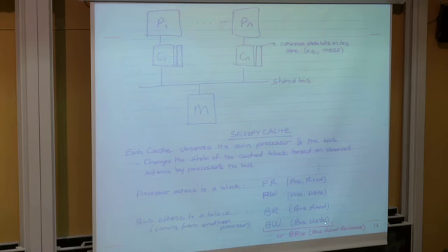Bus write can also be called bus read exclusive. They're not exactly the same thing. You can have a bus write and also a bus read exclusive, separate signals. Why? Because you might actually want to read the block exclusively, even if you are not writing to it at this point in time, right? In fact, several processors have these write hint instructions, if you will, to bring the cache block early before they actually write to them.